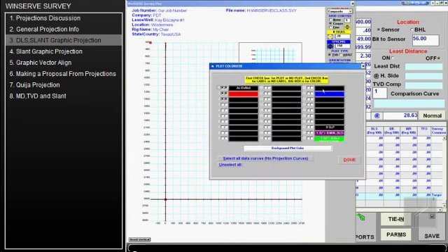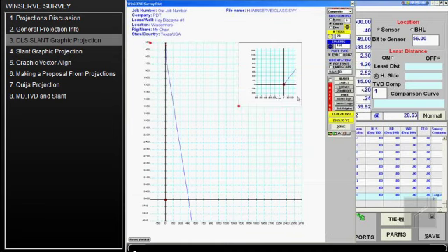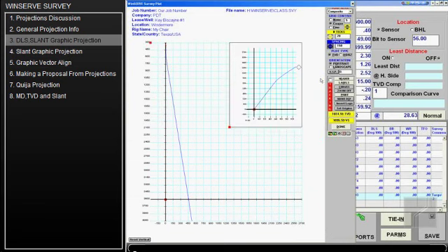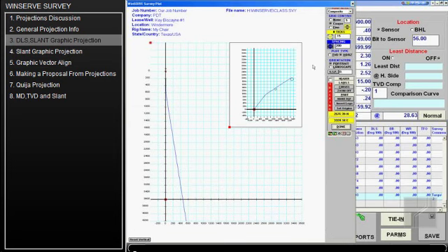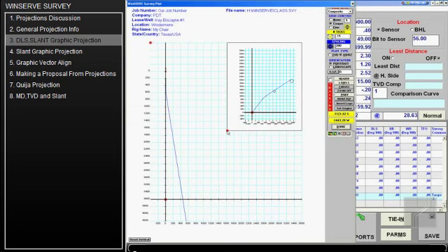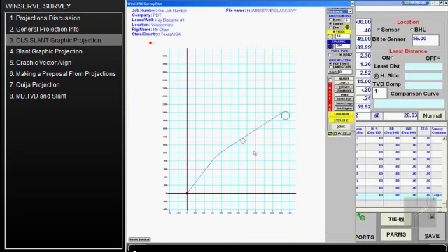And when I go to my plot and get my plot adjusted in the right way, we'll be able to see all that stuff. And I'm going to turn on my curve 21 projection. Again, we're going to be discussing the plots in greater detail here. For right now, you can see that I'm going to put this at 200 feet here. Adjusting, I need to click on this curve right here, 200 feet. I'm going to reduce the number of ticks here, or increase the number of ticks here so that I can see my other targets.